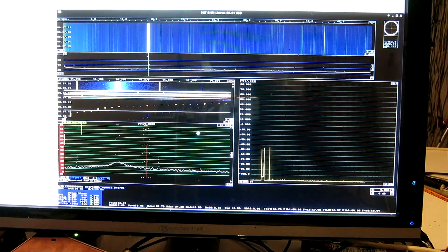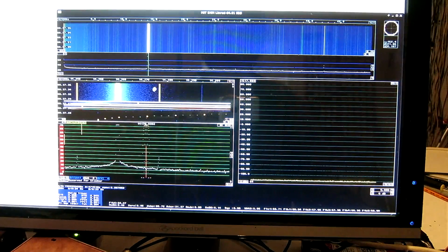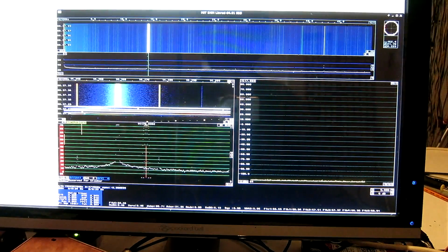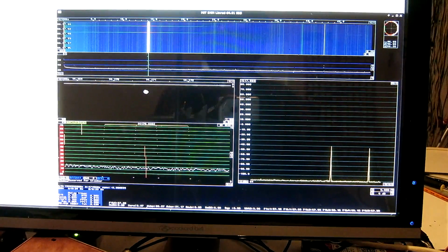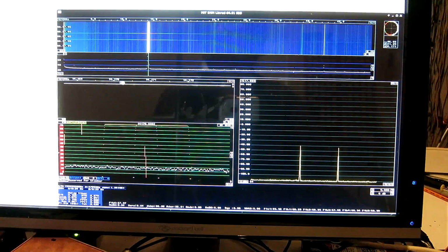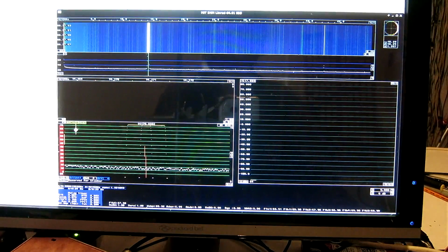I want to measure the sideband noise. To do that, I expand the frequency scale here in the baseband graph to maybe like this. It's 1 kilohertz from here to here. Means that I want a bandwidth of, let's say, 1 kilohertz for the measurement here. So this much is about as that much. To check, I grab the BFO and measure the frequency here,